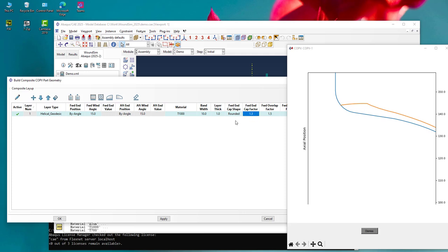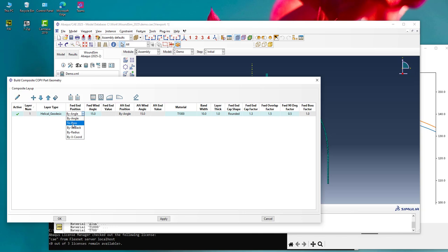Or what we could do instead is, we know that these things flatten out naturally as we get to the polar boss because they're being pulled around the polar boss. So we can terminate it a different way. We can say by to boss. Now you'll notice this all of a sudden says we don't have a wind angle. We'll calculate exactly where the wind angle is when it hits the boss. Alright, so let's resketch that.